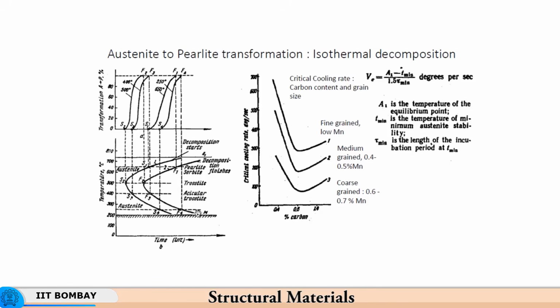So, that is why when the temperatures are low, the transformations are also a little sluggish, but then the driving force due to temperature not being present, the diffusion distances are very small, and therefore, you will get finer structures here as compared to over there.